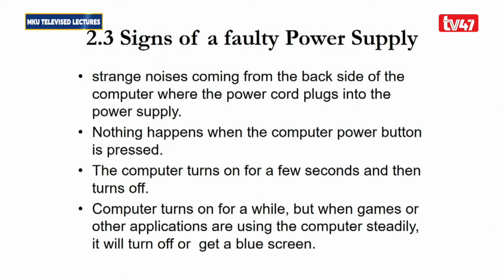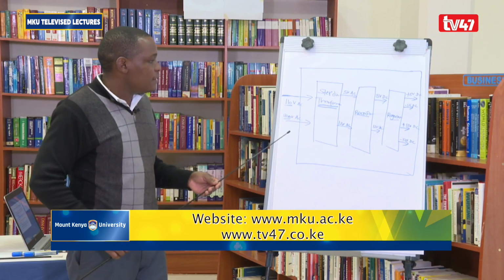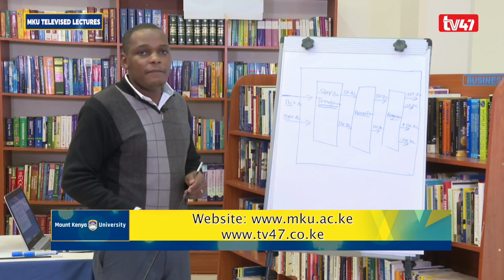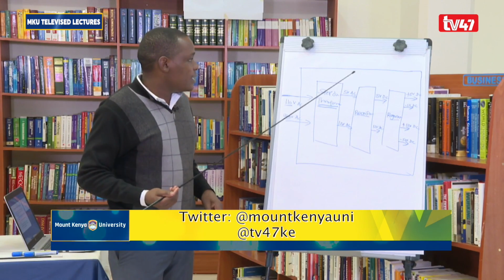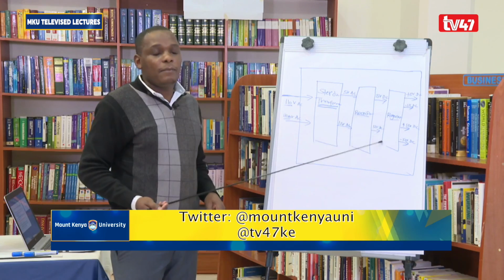But it is not advisable to open the power supply case when the voltage is on, because as you can see from this particular diagram, very high voltage is getting into the power supply unit, which may cause an accident or might cause death as a result of this voltage flowing into your body. It's quite high voltage that can result in serious injuries, and therefore it is important to ensure that you have a good ground in electricity when you are especially working with the inside of a power supply unit.